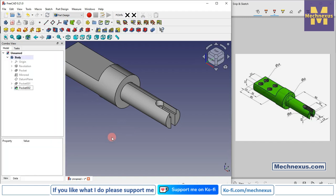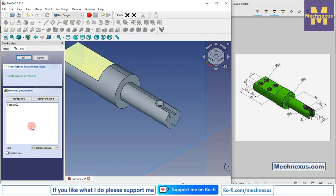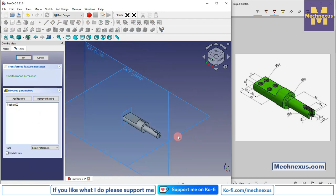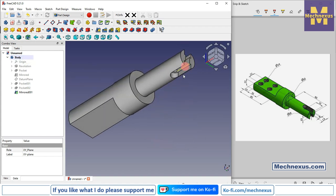click on OK. Now we will again mirror it on the other side, so select the mirror and select a reference and select this mid plane, click on OK. So now this cut has got mirrored on the other side.